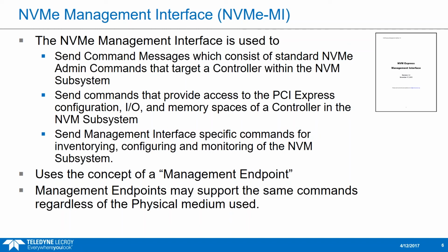So these are different types of commands for different areas in the device. It could be standard NVMe admin commands over the management interface. It could be PCI Express, for example, reading a configuration space register over the management interface rather than in-band through the PCI Express interface. And also specific management commands for the devices. You think, why would you want to be able to do this?